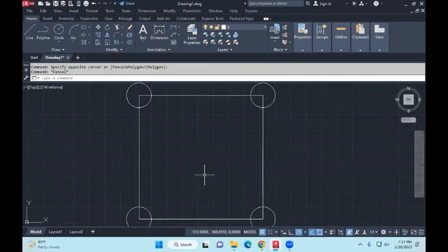Okay, let's take one arc. What I'd like you to do is trim it. Let's just remove the arc which is inside. Do that for one of the circles. For that, you'll have to trim it out, so look for the trim command or the trim button. Again, it's under modify. So in the dashboard, look for modify, look for where trim is, and trim it out.